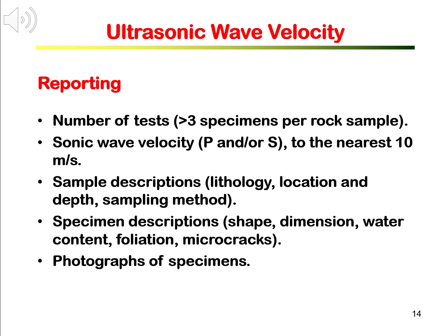The report should also include descriptions of the ultrasonic wave tester and the calibration history. In the report, sample and specimen descriptions must be provided, including rock lithology, sample location and depth, specimen shape and dimension, water content, foliations and microcracks inside the specimen, together with photos.